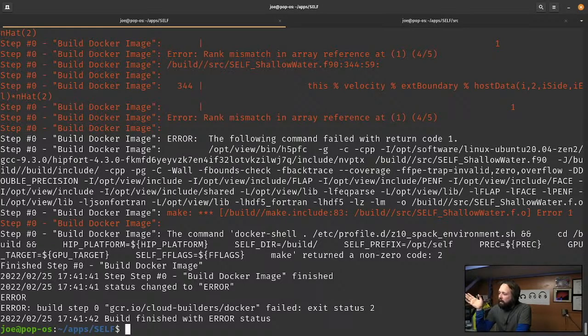So when you do domain decomposition, it is more or less ideal. It does, in some sense, try to minimize the amount of communications between MPI ranks. So I preferred to go that route where we just generate HOHQMesh meshes or Gmsh meshes and pass them through HOPR, and then SELF is set up to read the output of HOPR for simulation.